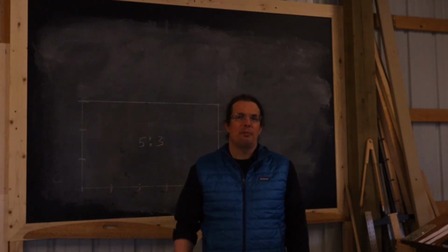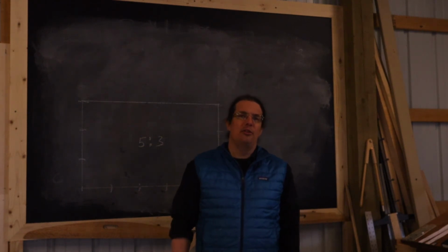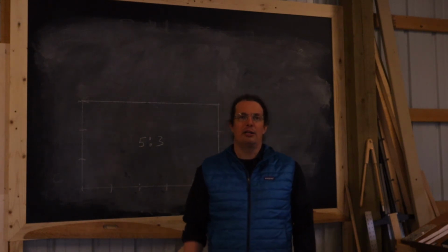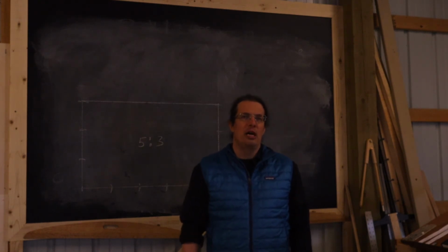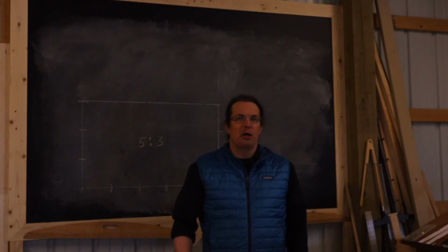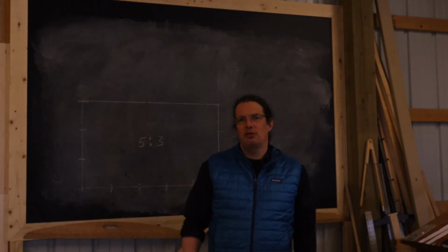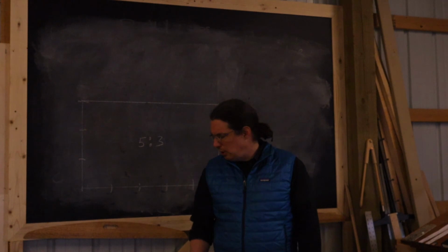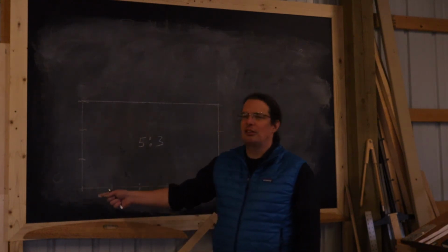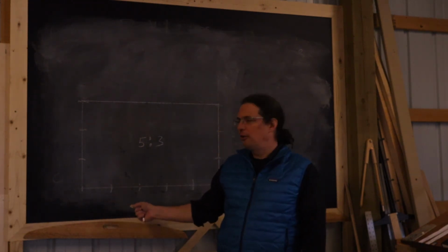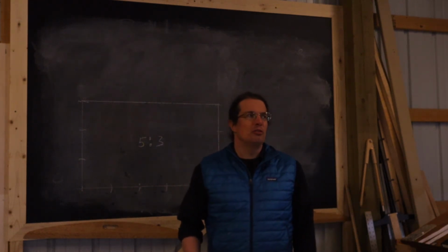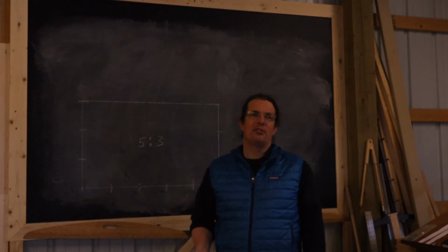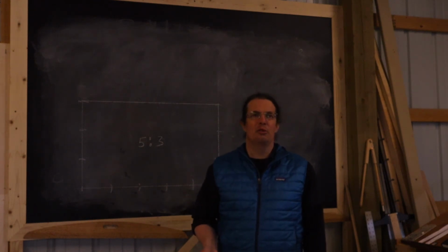And we know how to do that. We've got 3 ways to do that, in fact. We could use the parallel line construction for subdividing a segment into a chosen number of equal pieces. We could use the straight edge, layout square, and marked ruler construction for doing the same. Or in a pinch, we could even take our dividers and just iteratively adjust them until they are set correctly to step out 5 steps exactly along your baseline. Whatever way you choose, you've got to divide that entire segment up into your chosen number of pieces.